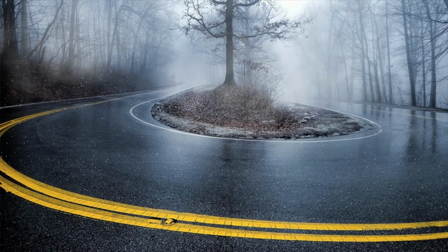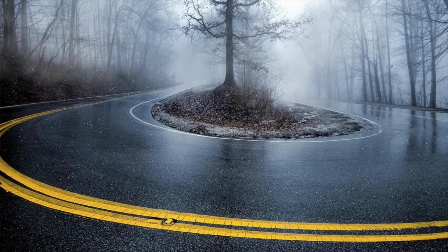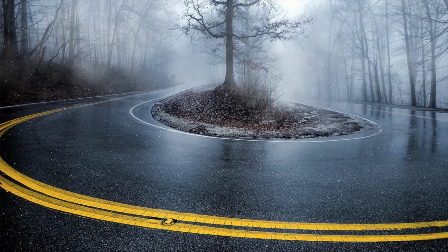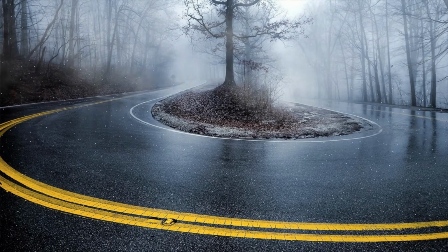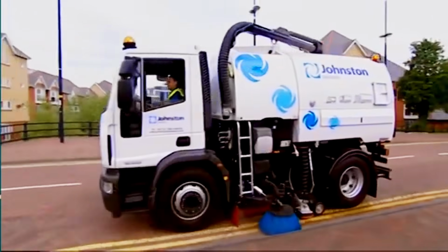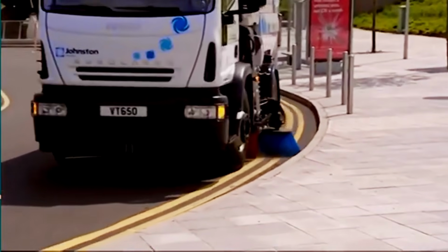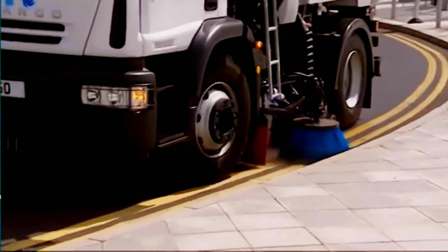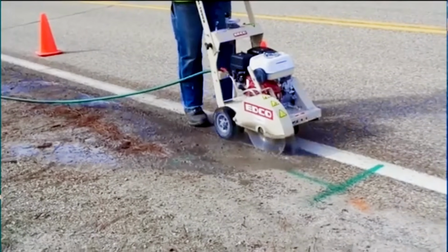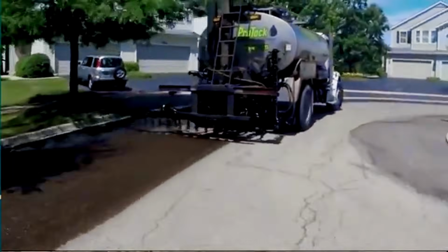Construction procedures to be followed include weather conditions. Laying work shall not be carried out during rainy or foggy weather, when the base surface is damp or wet, during dust storms, or when the atmospheric temperature in shade is less than 10 degrees Celsius. Preparation of the base is essential. The surface shall be free from dust and foreign matter. It shall be cleaned using a mechanical broom or compressed air. Transverse joints shall be cut vertically using an asphalt cutter, and a coat of hot bitumen shall be applied before placing the new material.